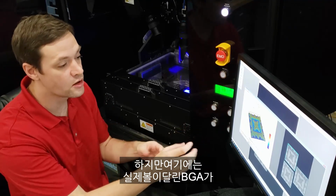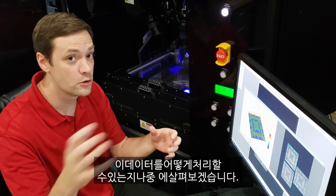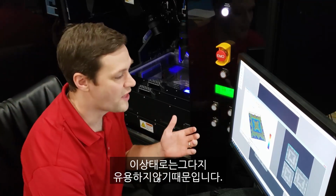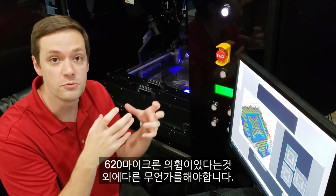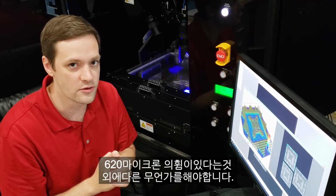But what you get here, I have an actual bald BGA, and you're actually going to get the solder balls. We'll look at this later and how you might process this data, because as it is, it's not that usable. I mean, it's cool looking, but what do you do with that information? We need to do something with it besides saying, hey, that's 620 microns of warpage.